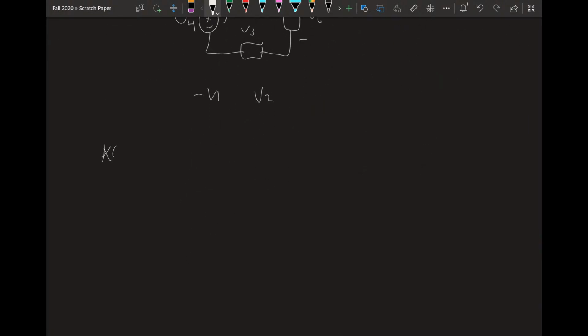Similarly, for Kirchhoff's current law, you have some sort of node with currents going into it. The sum of the currents into the node is 0. And just like KVL, you need some sort of sign direction. I choose to describe, and what I'll be using, is that the current going into a node is negative, and a current going out is positive. Oh no, sorry, that's not what I use. I use the opposite: current going in positive, out negative. So this would be positive, this would be positive, this would be negative. You can use the opposite. Anything works. This is just what is more natural to me.